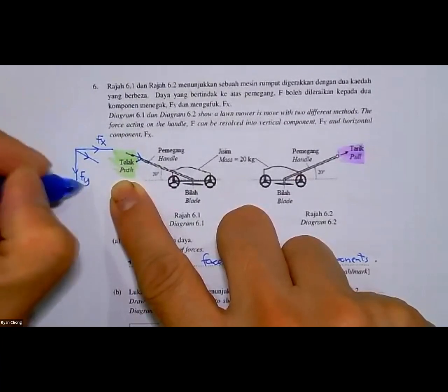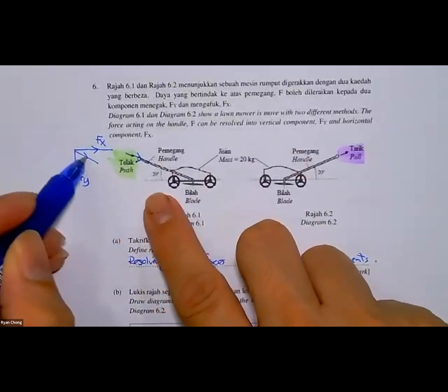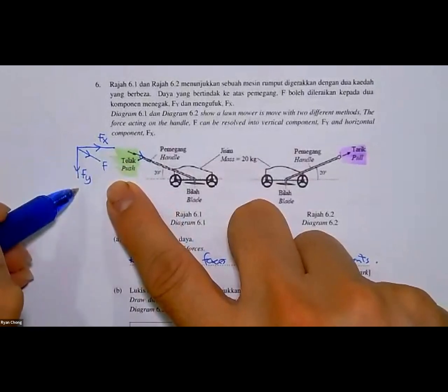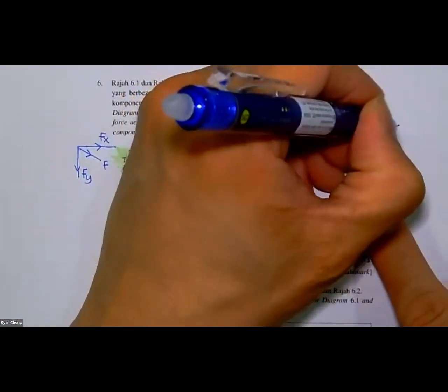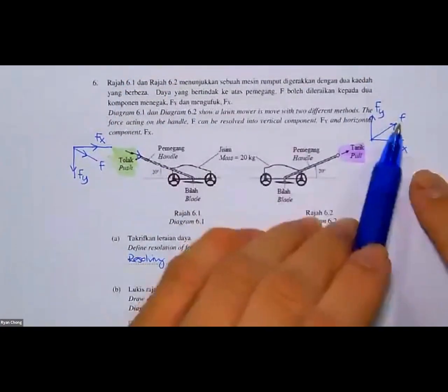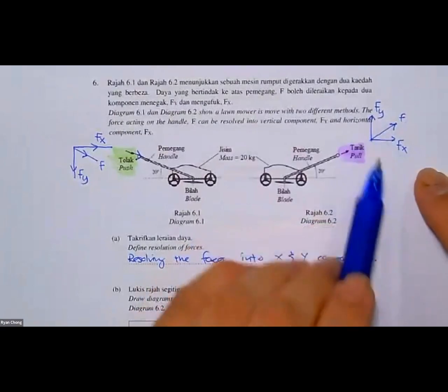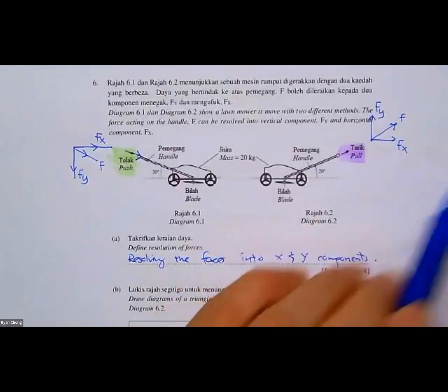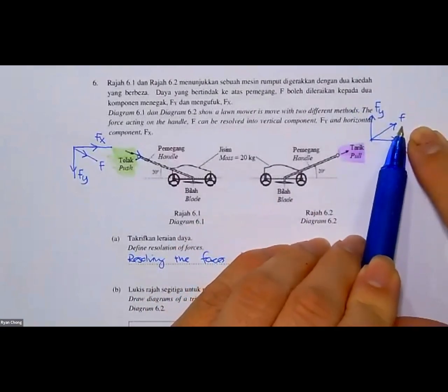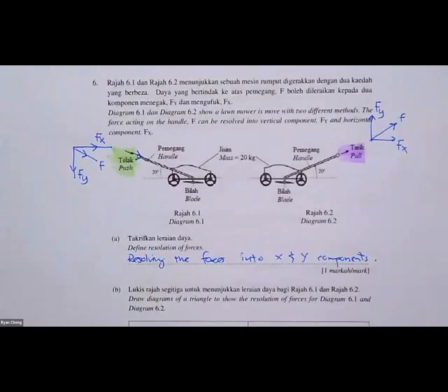and going down will be Fy, right? Because you want to have the resultant force in the middle. So when you resolve, it must be one up, one down. This one you pull up. That's why you will have your Fx horizontal going right and then Fy going up, because the F must be in between them. So horizontal goes right, vertical goes up to get the resultant force over here. So this is how I see the pull and push questions, how they are different.